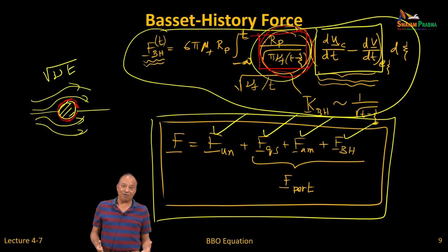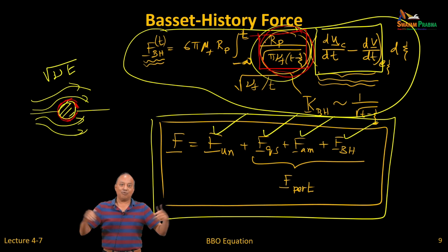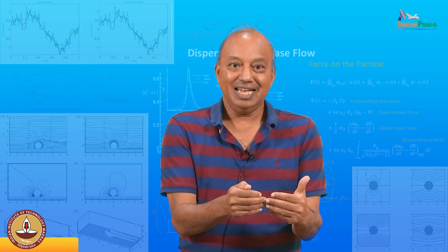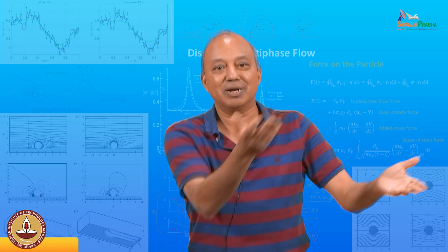In a steady flow, the Stokes drag, the quasi-steady drag, was easy because that is the effect of the fully formed boundary layer. Viscous effect, pressure effect, everything is steady, so you have nothing to worry about. Now when you change, it has to go from the old value to the new value, and it doesn't do it instantly. It has to build up. And that's the history term.